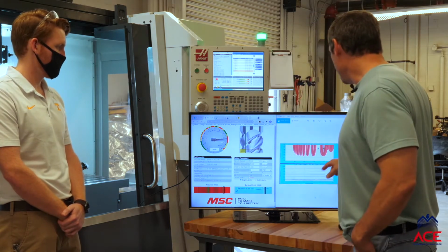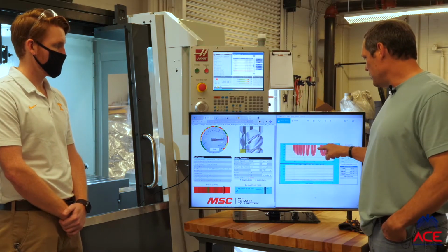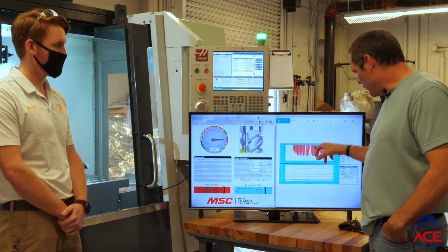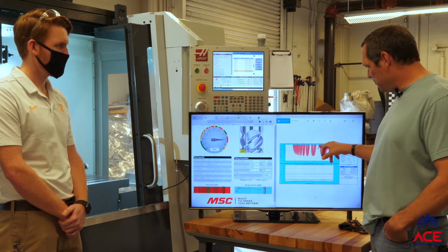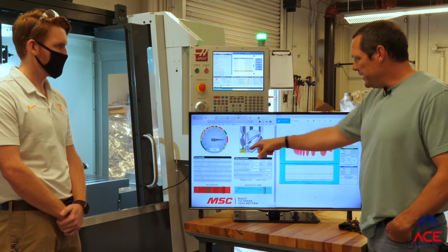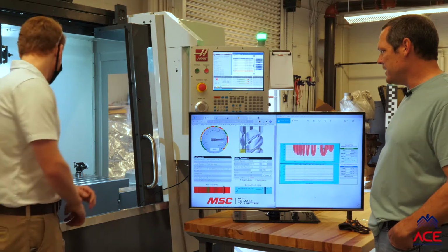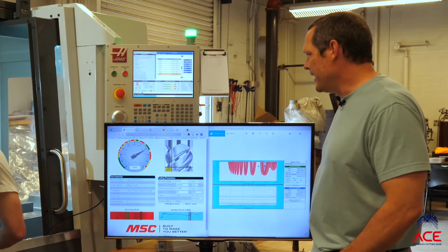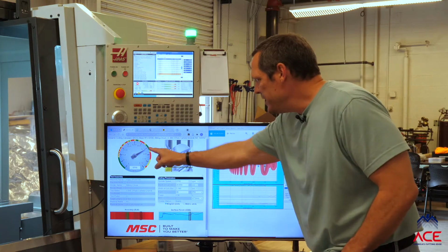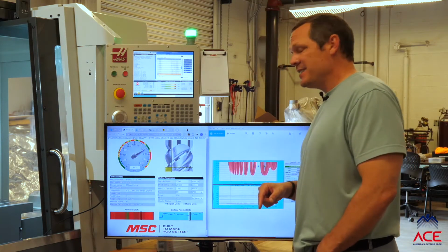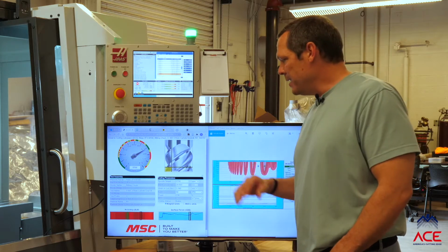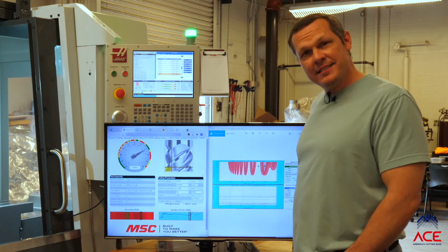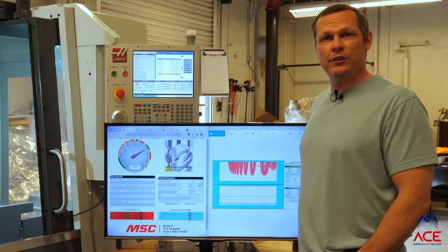Now, if instead we change our spindle speed to a stable condition, we can see that for the stability map, that would be the blue circle that we see, and then we can change the spindle speed here to the stable cut, which is 5,700 RPM in our case. And now we've moved into the green zone, and we would predict stable cutting conditions by the MSC dashboard. Okay, so let's now proceed to our cuts, and we'll be able to see and hear the difference.